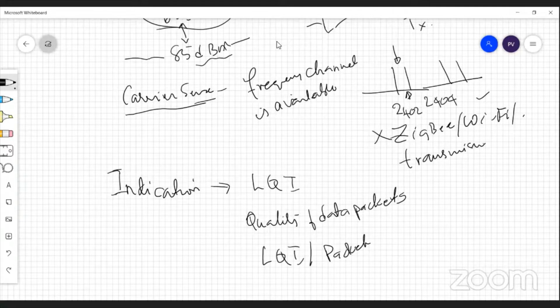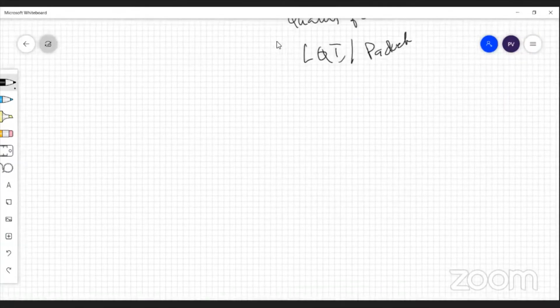Now, how do you assess whether a channel is free or not? Again, there are three modes in this whole thing. There is something called CCA mode 1, then mode 2 and mode 3. In mode 1, you have learned about energy detection, right? Somehow you must get the 15.4 MAC configured to use these things that we learned, either carrier sense or ED, energy detection.